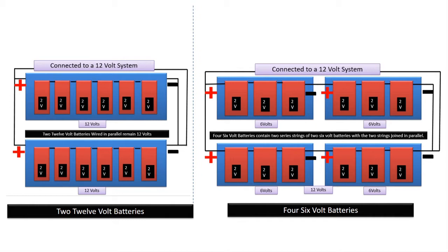Your charge controller battery charger sees each system as a single 12-volt battery bank electrically. For electrical purposes, there's very little difference between the two systems. There are some physical differences in plate thickness, charging rate, longevity, and quality, and any one of the system configurations can work for your application, provided it stores the amount of energy that you need.